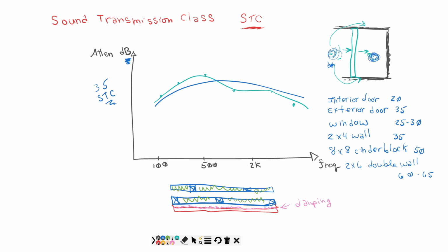And then you would apply the second layer of drywall, and you would stagger them so that the seams don't line up, right? And what happens with the damping material is it basically turns the impinging sound wave that's coming in here into a shear force. So you could kind of think of this as like a gooey, sort of gluey, rubbery kind of thing. It never dries fully, right? So the sound comes in and you create this little shear force in here, and that absorbs a lot of sound, right?